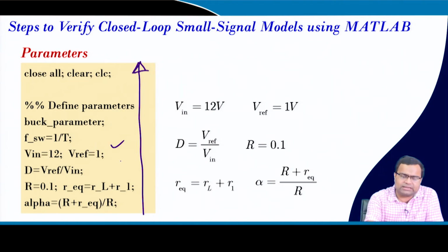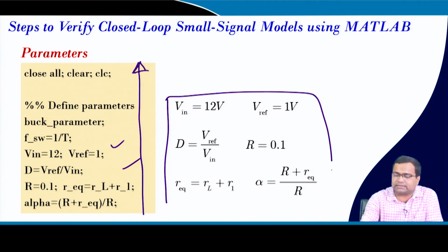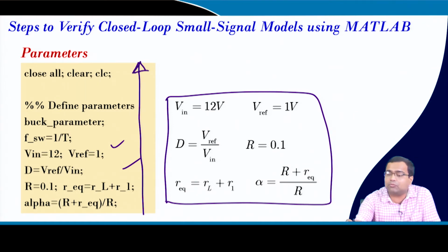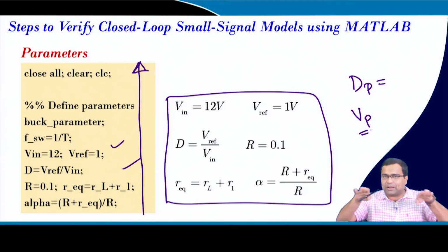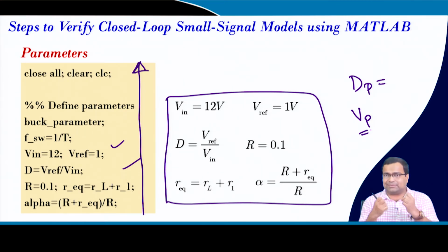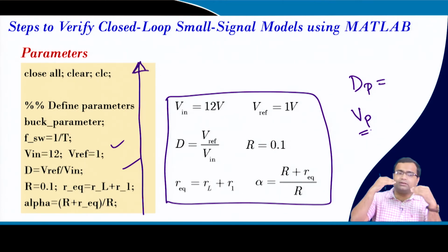So, these things are already discussed in that lecture number 13, and these all are equivalent, etc. is explained. But now here we do not need a practical duty ratio. Why? Because in the earlier case we needed a practical voltage, because it was open loop. We obtain the AC simulation and transient simulation from the small signal, and we wanted to add that AC small signal response